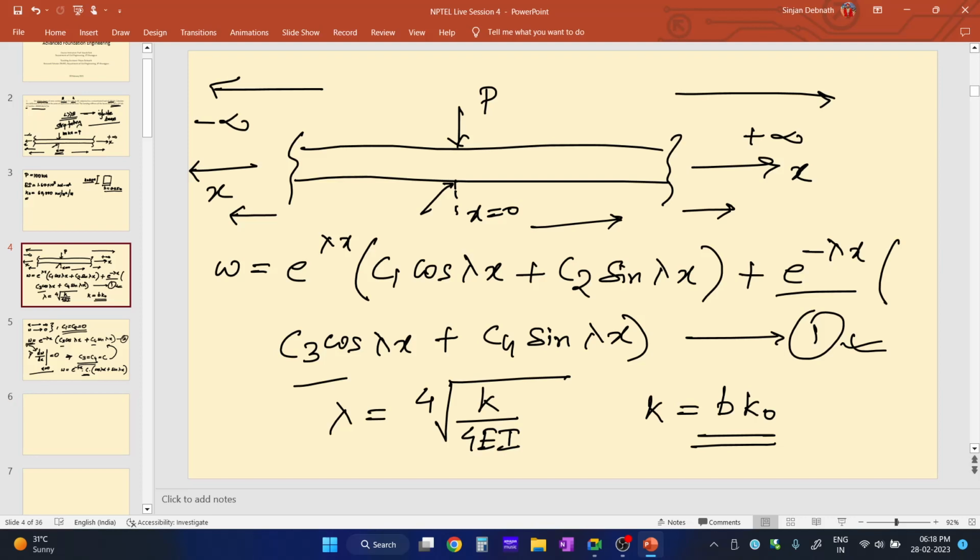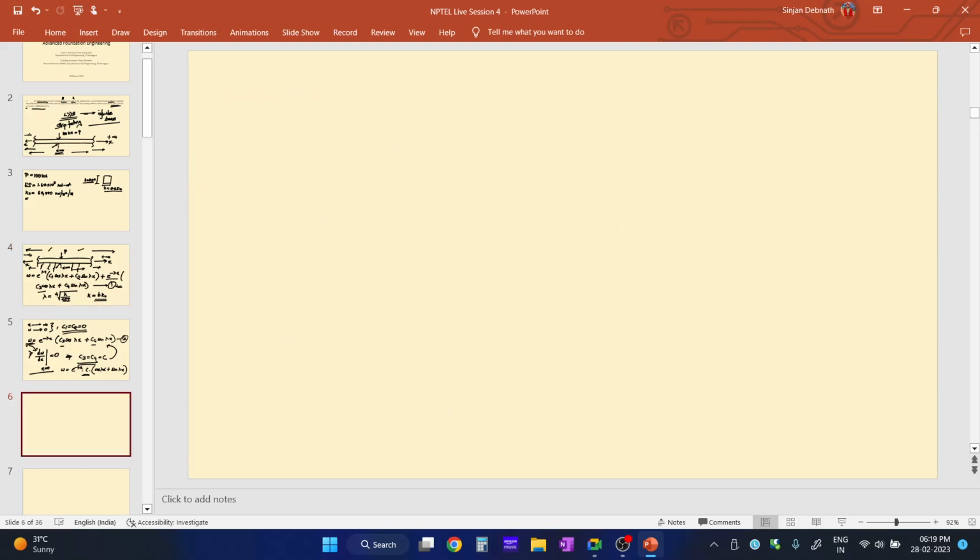That means, as I told earlier, there will be soil underneath this beam. The soil can be represented using springs, so there will be springs like this. What happens in soil? You are applying the load on the footing, and the soil is also providing resistance, right? So the springs will also provide resistance. Since this is symmetric, with the load acting at the middle, we are just considering the left part or the right part, any one among them.